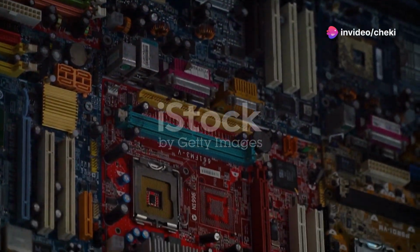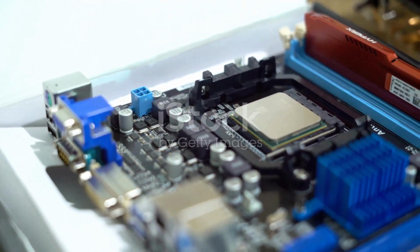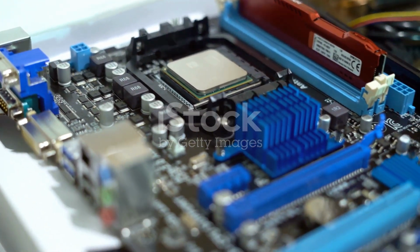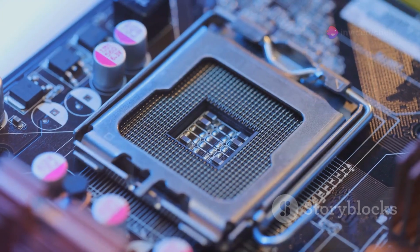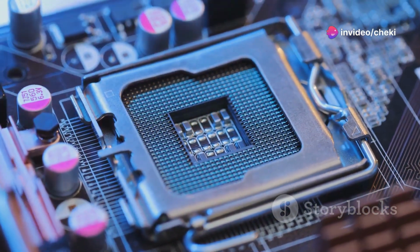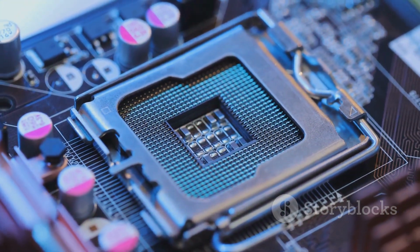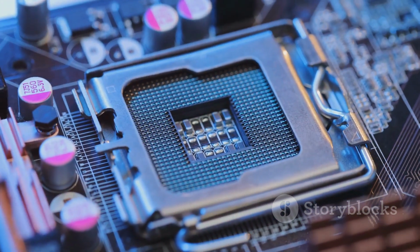Section 5. Power and stability, keeping it running. The VRM, or voltage regulator module, is responsible for delivering clean and stable power to the CPU. A high-quality VRM is crucial for overclocking and ensuring stable system operation under heavy load. It ensures that the CPU receives the correct voltage, preventing instability and potential damage.